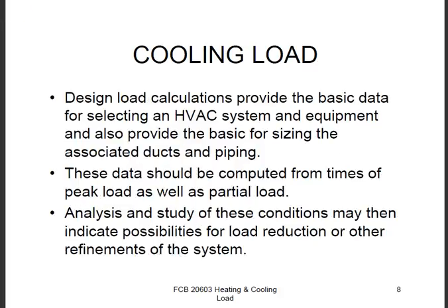Design load calculations provide the basic data for selecting an HVAC system and equipment, and also provide the basis for sizing the associated ducts and piping. This data should be computed for times of peak load as well as partial load. Analysis and study of these conditions may then indicate possibilities for load reduction or other refinements of the system.